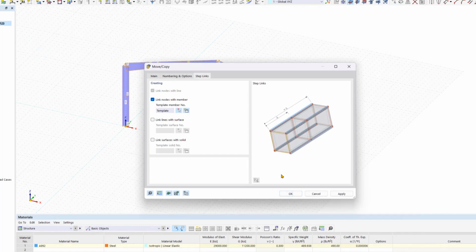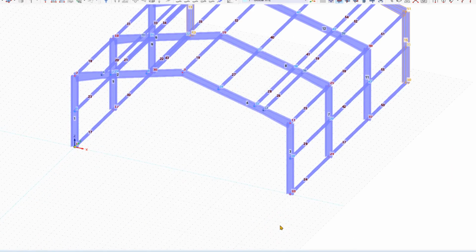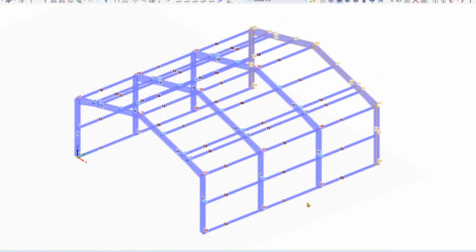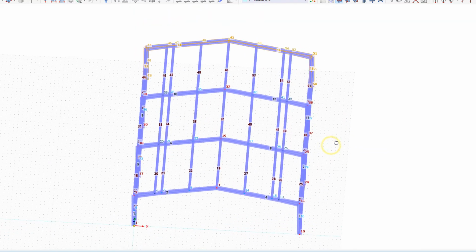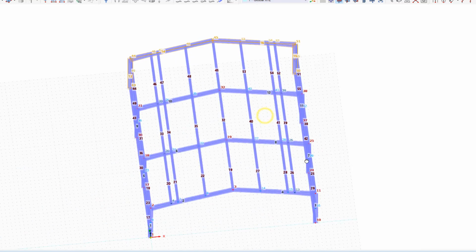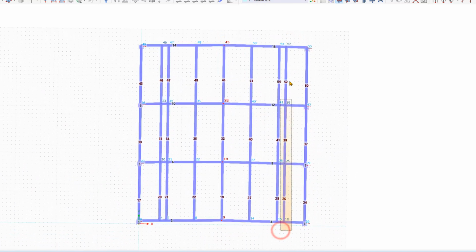The section is taken over, and a 3D hull is now created from a two-dimensional frame. The stiffening members at the start of the taper are superfluous, so we delete them. We can simply select them from left to right by holding the Control key, and then we can hit the Delete key.